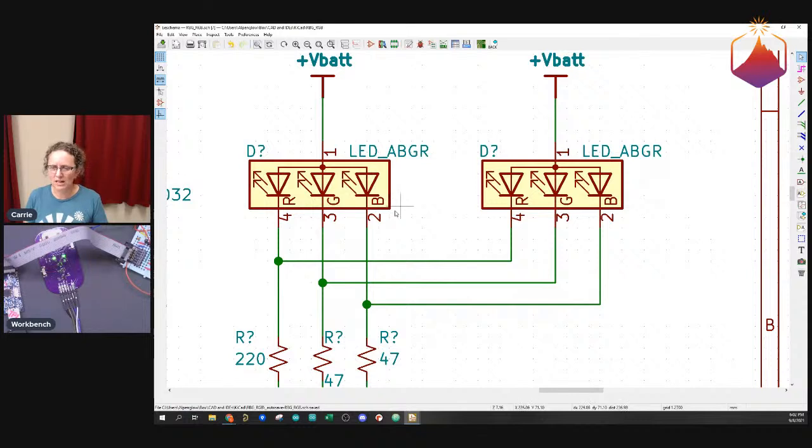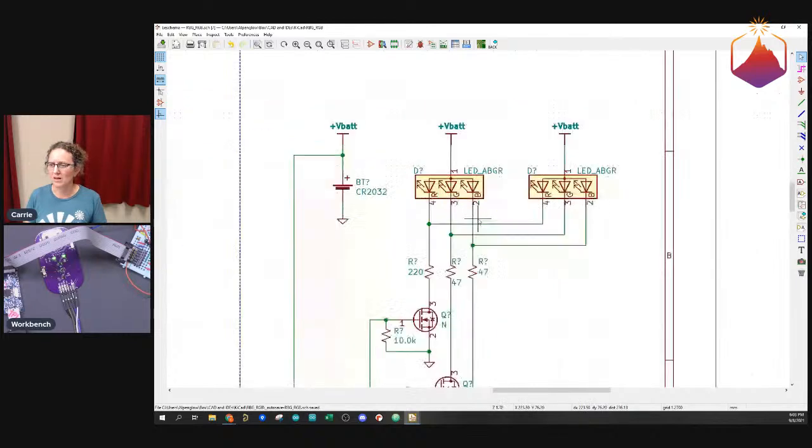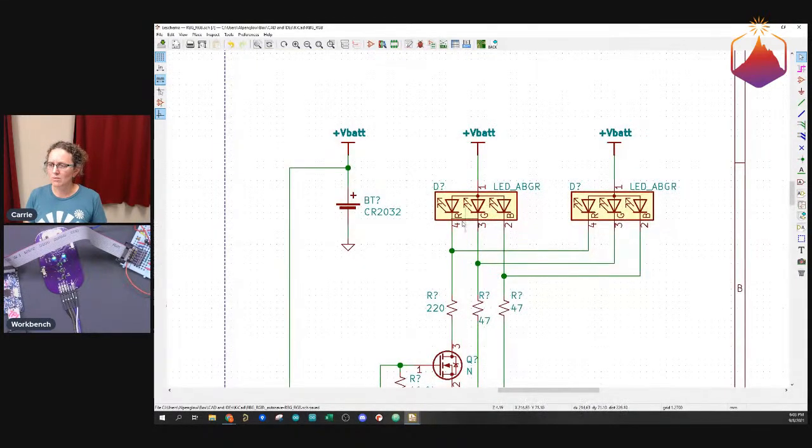I think it's pretty obvious if you have 1 designator by 3 things that are in a different color and obviously grouped together. Like, oh, it's obvious that this is a single RGB LED and not 3 individual discrete LEDs. So I just feel like the symbol has a lot of visual clutter, especially if we're zoomed out. And it also bugs me that the RGB is sideways. This is a schematic. You're only going to be looking at it in one direction. I feel like your text should be in the direction of reading.